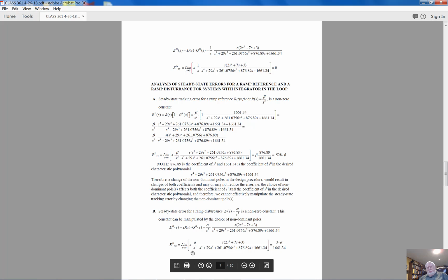We're going through algebra and we're doing the steady state error caused by disturbance. We have s of the final value theorem. We have s squared in the denominator. If you remember, this s in the numerator of the transfer function appeared because of the integrator, and as a result I'm getting a constant for you.